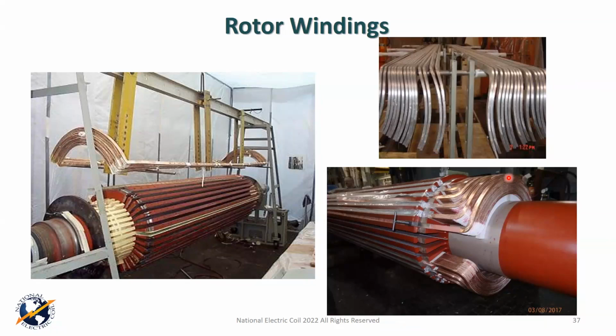But the Alstom braze joint is in the middle. The original design is really only good once. You can't rewind it and have that connection remain as it is for that rewind and reuse that conductor. However, the good news is, at least for us, and I think Alstom has found a fix too, we found a fix where we incorporate a new connector and can still reuse the copper and get away from the fragility and the mechanical problems they had in that braze region.